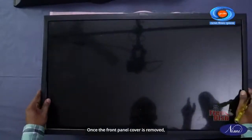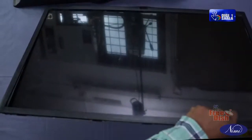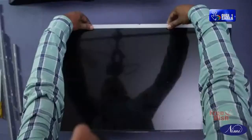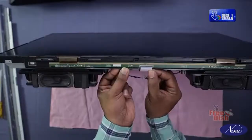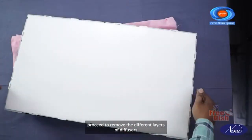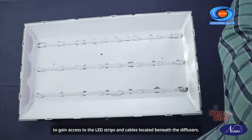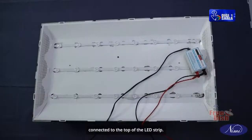Once the front panel cover is removed, place the display screen on a soft cloth or a padded surface to prevent any scratches or damage. With the display screen secured on the soft cloth, proceed to remove the different layers of diffusers positioned behind the screen. Additionally, remove one layer of reflector material to gain access to the LED strips and cables located beneath the diffusers. Finally, carefully unplug the cables connected to the top of the LED strip.